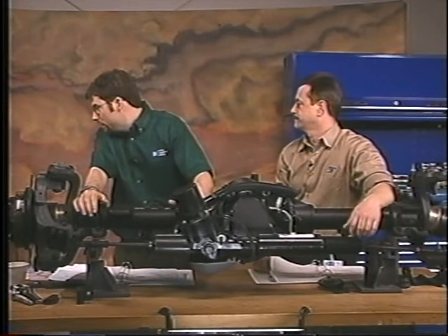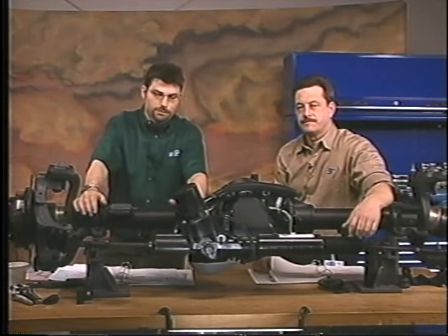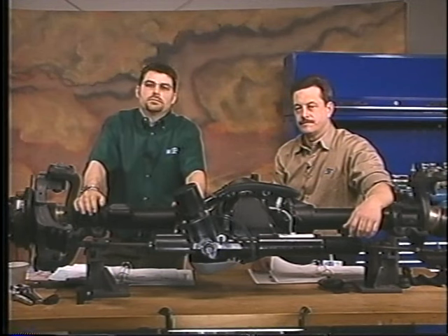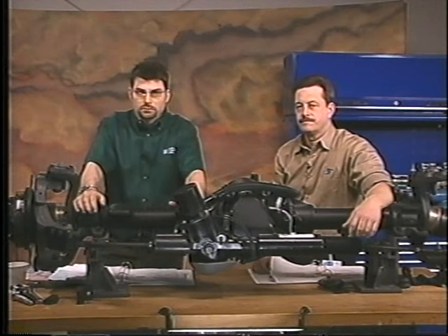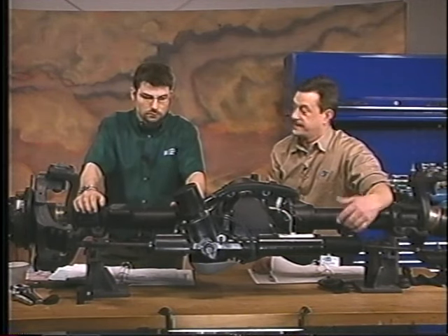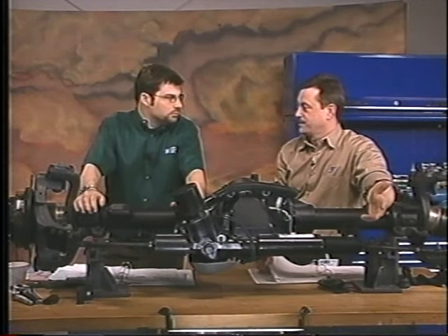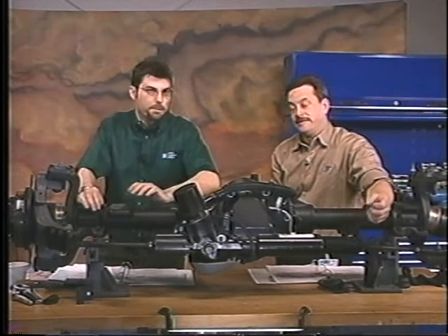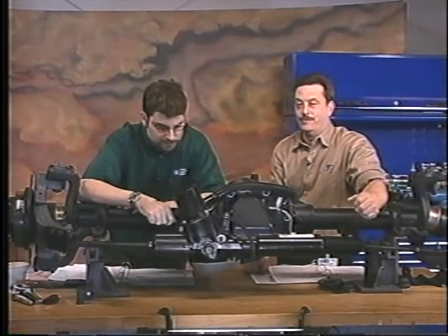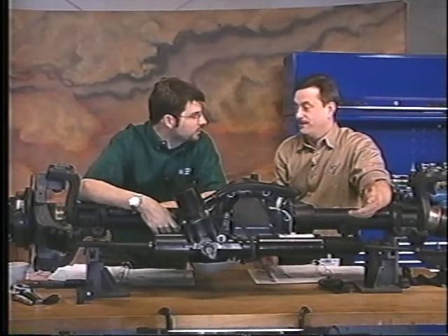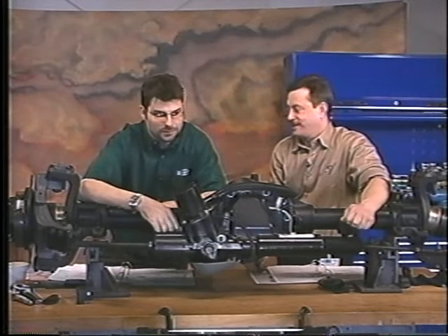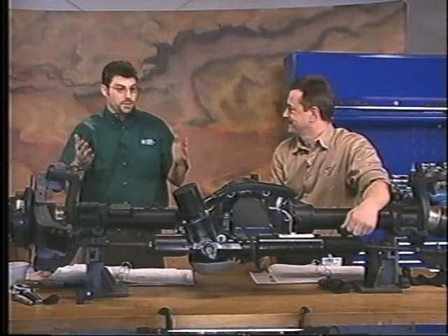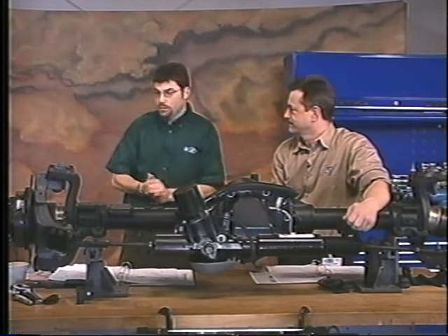Now, next we have Eric calling in from Roy Robinson Chevrolet. Next input, go ahead. That vehicle sensor definitely does know which phase to operate in. Yep, that's a good point. We can talk a little bit about what we're using those for as well. So the steering position sensor is telling us what direction we're turning the wheel and how far we're turning the steering wheel. Obviously, that has something to do with how far we turn the rear wheel in the direction. That's probably pretty important for the module to know. And then we've got the vehicle speed, because we have that 45-mile-an-hour cutoff, so we have to use vehicle speed for that input. You bet.